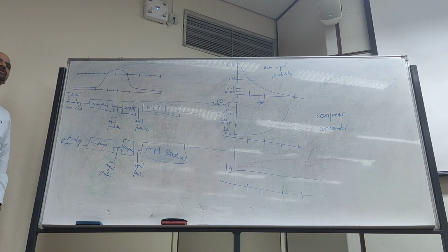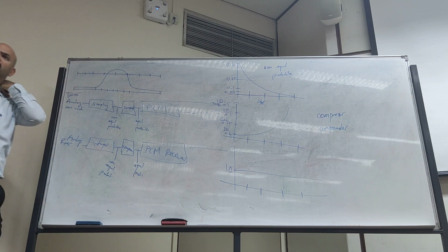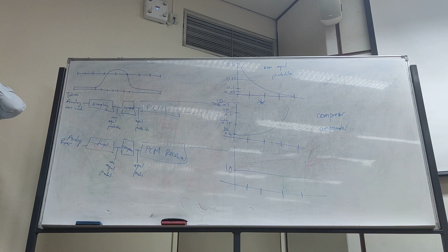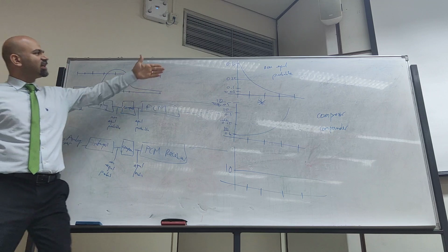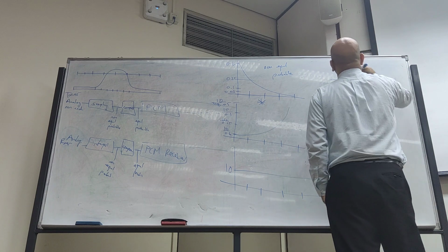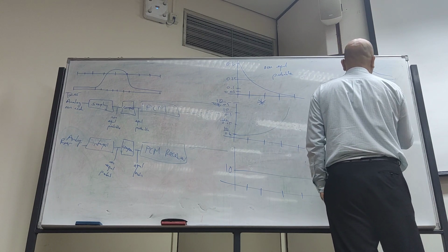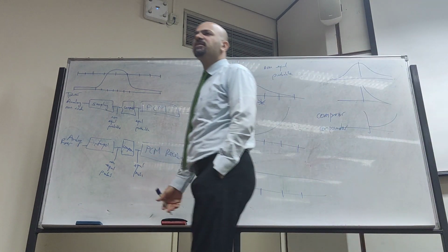Good. So, last comment here that I asked, and then I stopped. If here we did this compression, how will the receiver know it? Because the receiver has to reverse it, right? It will be equal, so it will convert to non-equal. But how will the receiver know that the input signal was exponential and it has to reverse it? Because here the input signal could be any distribution. It could be like this, or like this, or like this. How will the receiver know what the transmitter did?